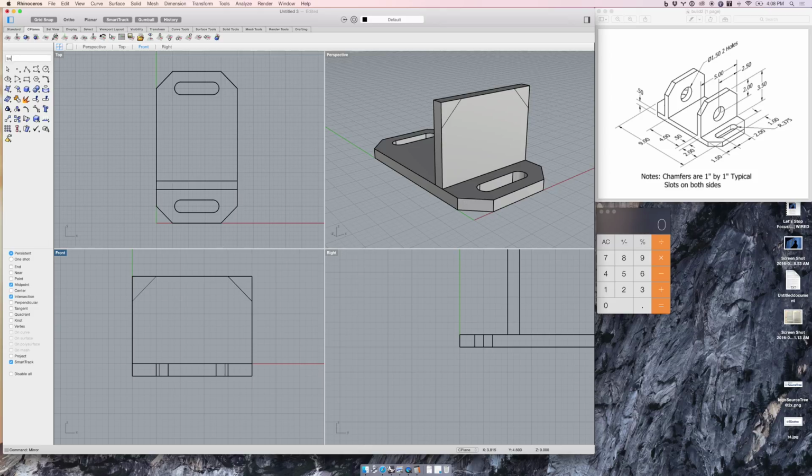And then I'm going to draw my guidelines for the circle. So midpoint guideline. And then I think I want the next one 2 inches down from the top. So there's 1 inch down and 2 inches. Now I'm having an issue. It's trying to snap to midpoint, and I actually don't want it to snap to the midpoint. So I'm going to turn that snap off. I'm going to go down distance of 1 inch, 1.5, 2 inches.